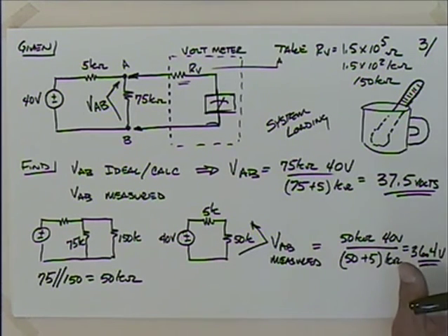And there's precautions that we'd probably want to take there. We may want to make an estimate of the temperature and bring the thermometer up to that temperature before we put it in. Maybe use a thermometer that has a minimum amount of thermal mass and things like that. So these are all things to think about, and in this case, a good example. It gives us some practice calculations as we go through this.